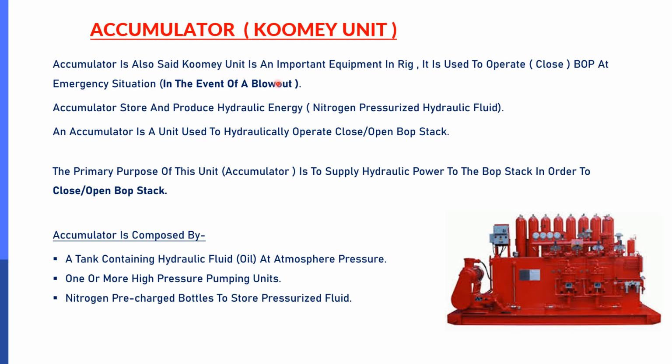It is an important equipment in the rig. It is used to operate or close the BOP in an emergency situation, which means in the event of a blowout. When the BOP drill is conducted, the accumulator should open and close in 60 seconds. This is the IADC standard. The accumulator stores and produces hydraulic energy, which means nitrogen pressurized hydraulic fluid.